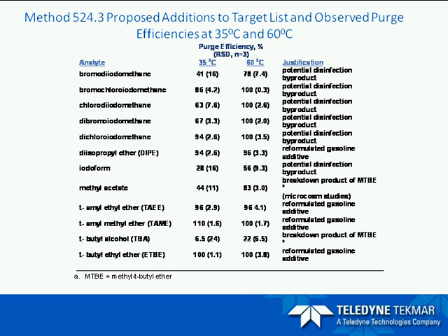So that's why they've been included as possible additions to the list. Now, the fuel oxygenates, which are present in reformulated gasolines, are introduced into the ground water by leaking from those underground storage tanks and are more invasive than the major constituents of gasoline itself because of their high water solubility. So, of course, with that information, you can see why they chose to try to include as many of those as possible in the proposed 524.3.